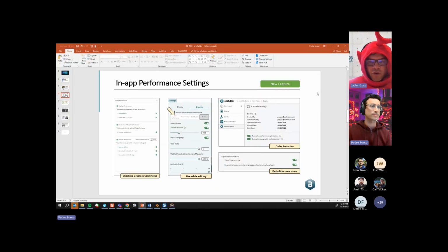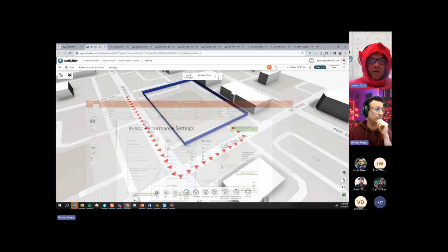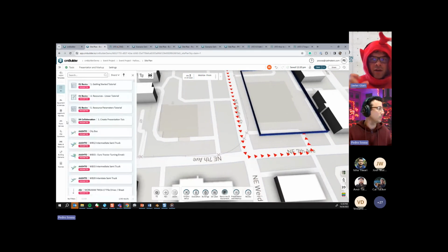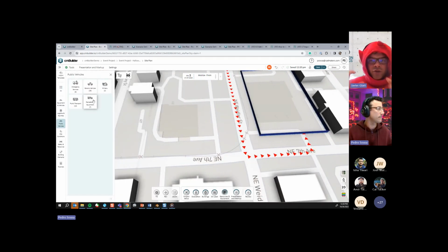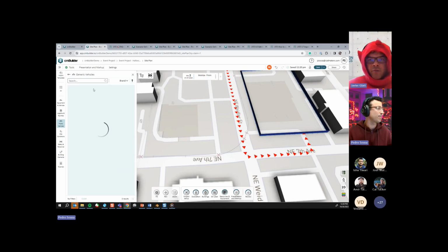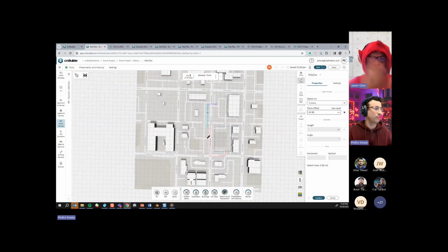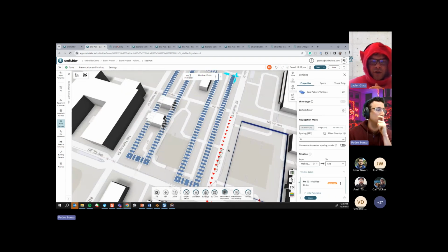Cool. Yeah, so things to look for. This is more of a technical workshop. Think of things to look for if you've used a polyline to generate a bunch of cars in a parking lot, right? So you have a whole whack of cars there. Previous to having that set, the system is rendering each of those cars and loading each one of them in memory. This automation will basically take one of them and instance it. So long and short of it, it'll be much better performance: run faster, load faster, and just work better. So yeah, go ahead.